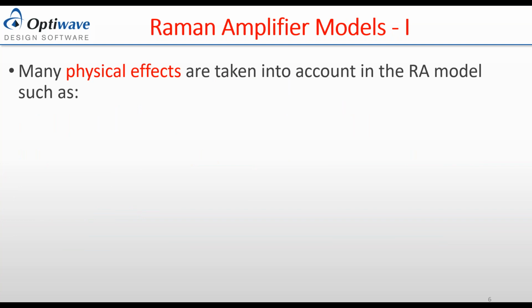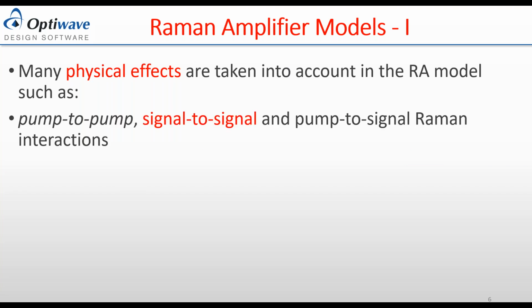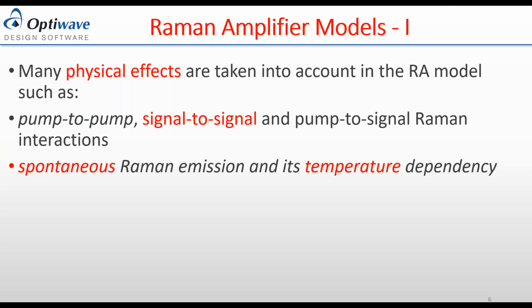In this part, we're going to talk about the models used for the Raman amplifiers. In these models, we consider many physical effects, where we calculate the pump-to-pump interaction, signal-to-signal interaction, and pump-to-signal interaction. We also consider the Raman spontaneous emission and its dependency on temperature.